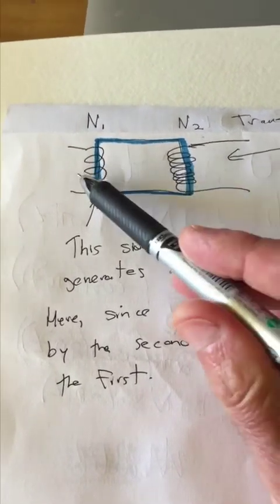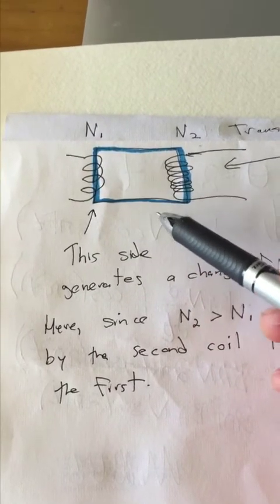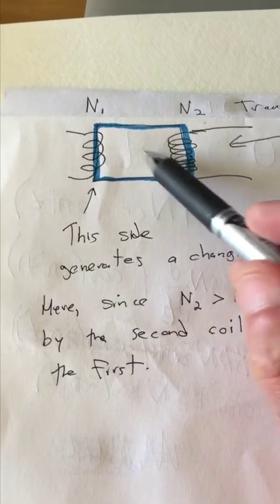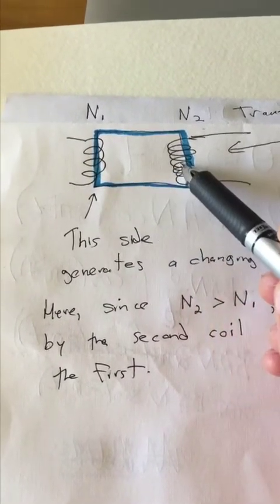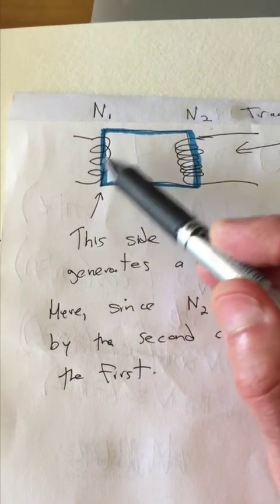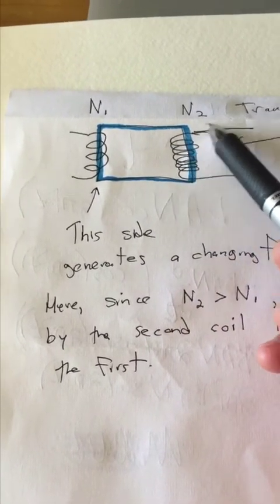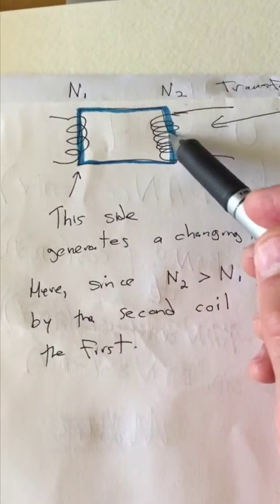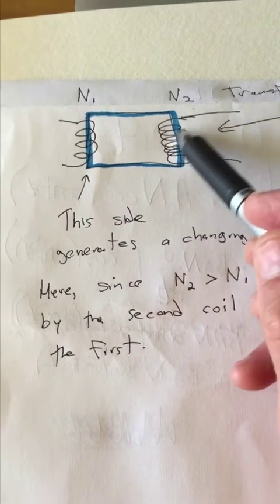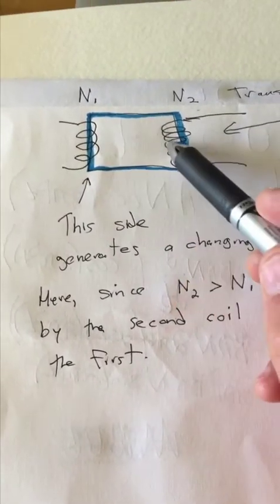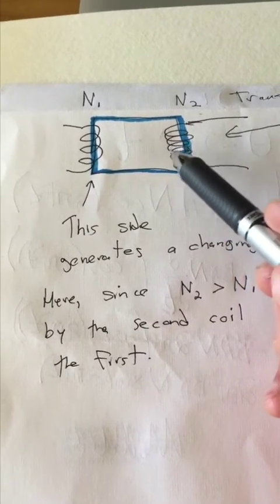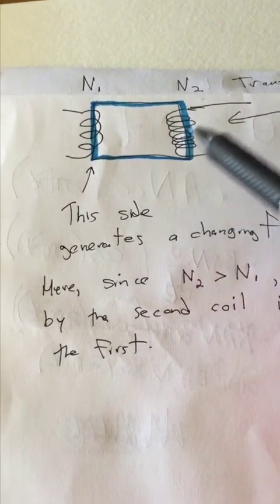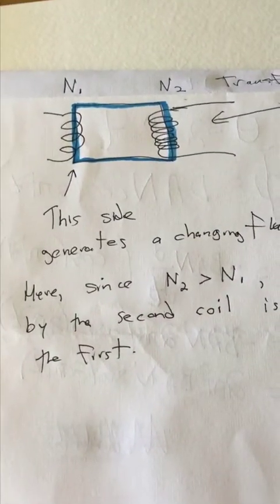And the other thing, you might have seen an example of this working, is an electric toothbrush that charges on a charger, but there's no connector, there are no wires. You actually have a coil of wire here and a coil of wire there. They share the same flux, so when this one varies, this one picks it up, and it's able to charge a battery from that. Without actually having physical electrical contacts, you're able to generate power over here, which is great because contacts can wear out. There's opportunity when you have contacts that they can get corroded, all sorts of things. That doesn't happen in this situation here. More in a subsequent video.